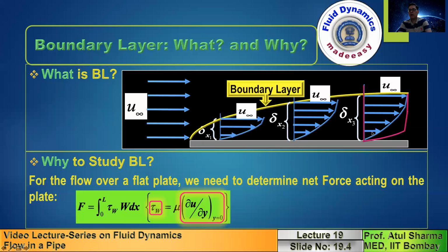Whereas in a turbulent flow, a fluid particle along with the u velocity also has a small v velocity, which is periodic in nature, with certain amplitude which changes from positive to negative. So the fluid particle moves upward and downward with respect to time, and it is chaotic motion, which leads to a better momentum transport, mixing of the momentum, and a much larger velocity gradient near the wall.